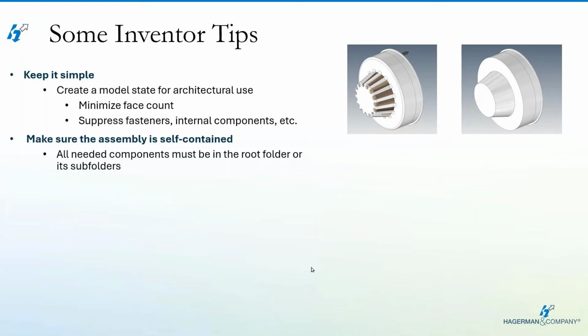Have them be local. Any other common folders you might have set up for your normal Inventor project file, you need to bring them down local, and you will make a local project file just for that one family. Okay, next.